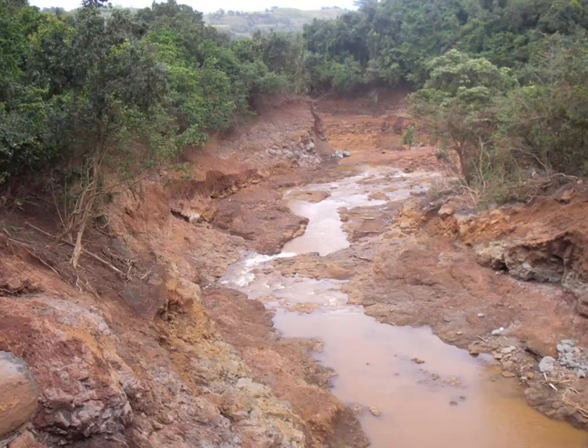But then when you pave over that with concrete or asphalt, or you put a roof that's not permeable, you're increasing the amount of impervious area, and that'll increase the runoff flows that make their way through streams. And so this is one of the side effects of human development, is that always the streams around us have a lot higher flow rates going to them during storms than originally before construction was put into place. And so the consequence of that is that the flow depths will be deeper than they would have ordinarily been.